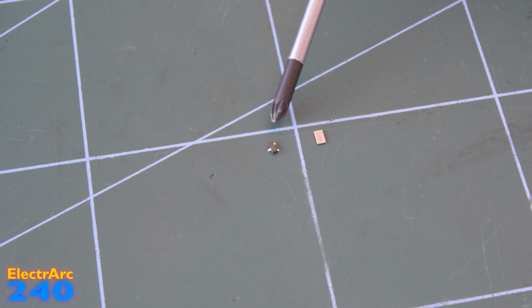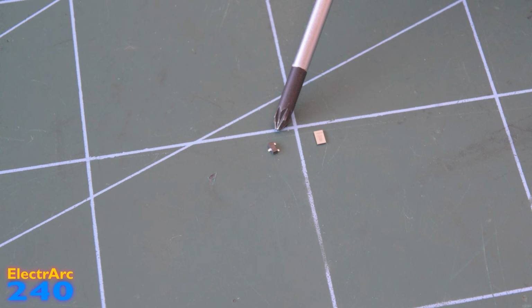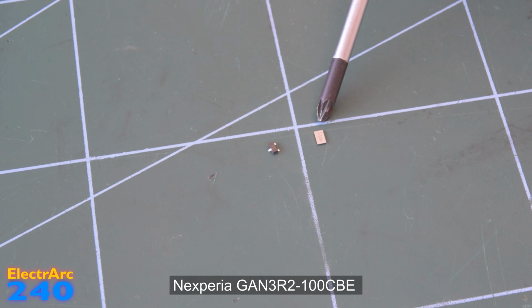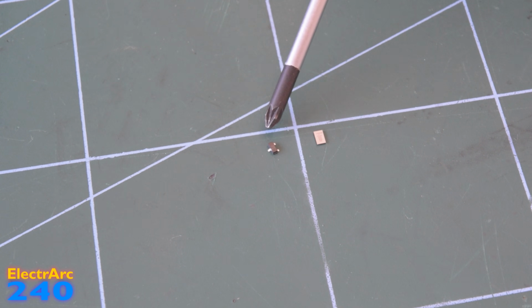This little MOSFET is the humble 2N7000. It's rated to block a maximum of 60 volts when it's off, and it's rated to conduct a current of up to 200 milliamps when it's on. For comparison, this gallium nitride device from Nexperia is able to block 100 volts when it's off and conduct 60 amps when it's on. That's right, 300 times the current of the old silicon MOSFET.